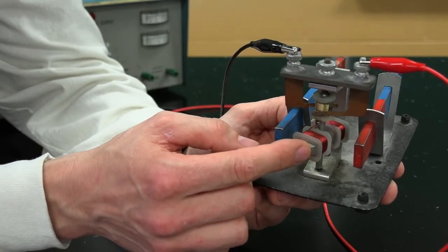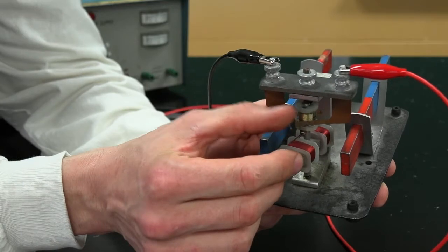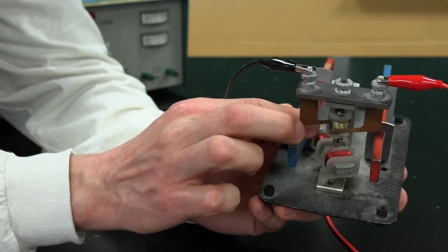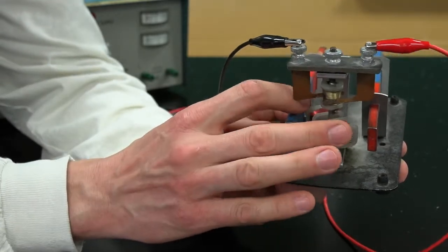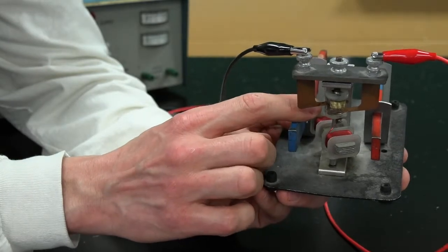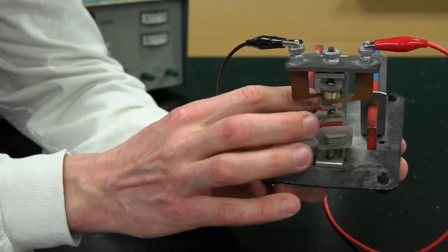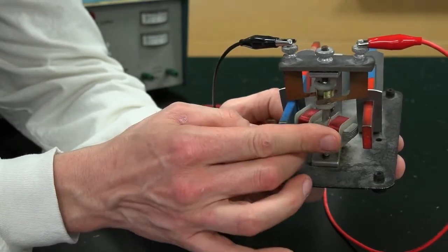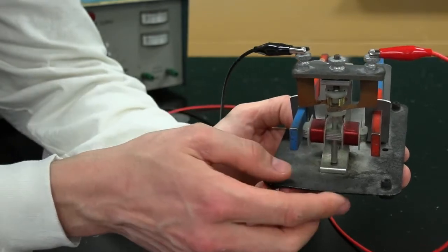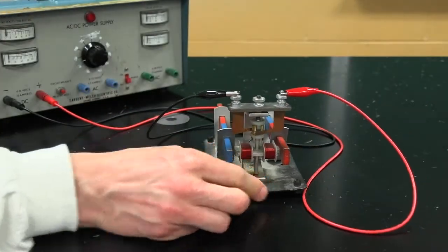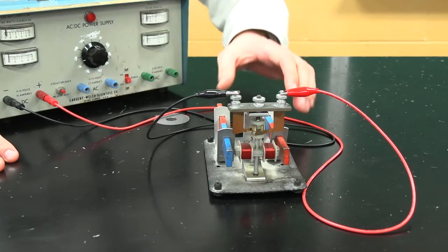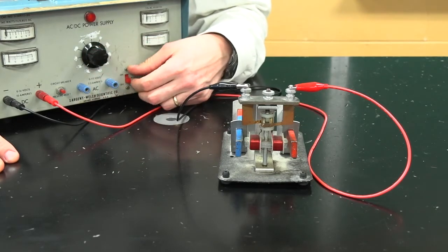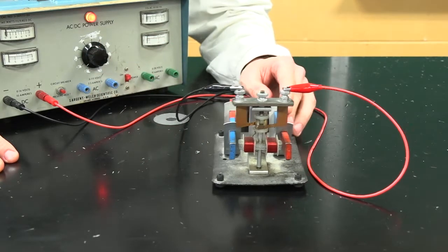As the motor spins, you see that now this metal plate on this axle loses contact with the positive and comes around and touches the negative brush over here. And what used to be on the negative side over here has now come around and touched the positive. So as this spins, the brushes automatically change the direction of the current continuously. So now what I'm going to do is put this here and pass an electric current through that coil, and we'll see that the brushes allow the coil to flip continuously and spin the motor.